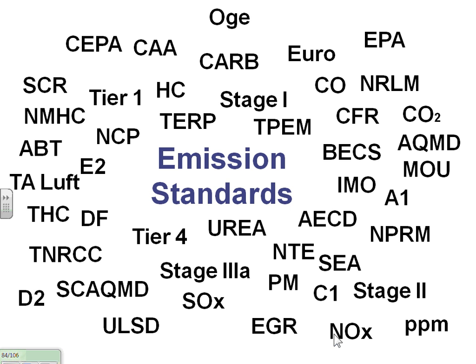But it's another commodity that this diesel generator set is going to consume. So we've got more consumption. In addition to the diesel fuel, now we're going to be consuming urea in approximately a 1-to-7 ratio, urea to diesel. So it's making life hard for us.